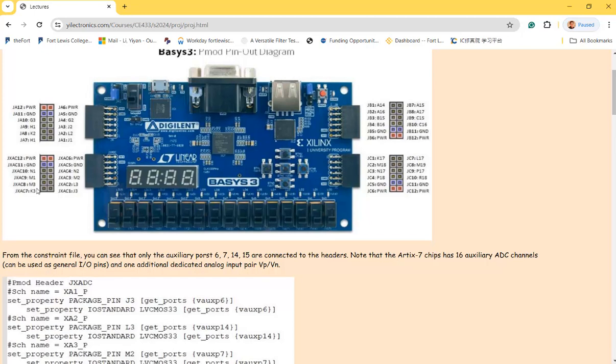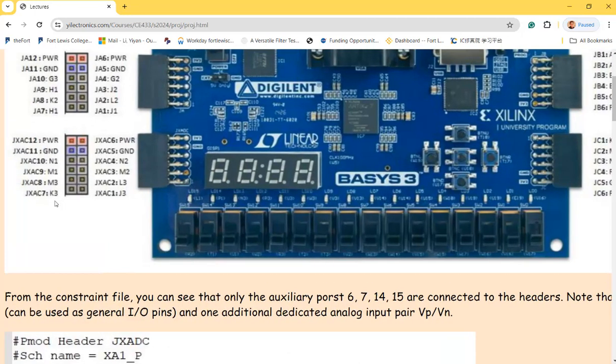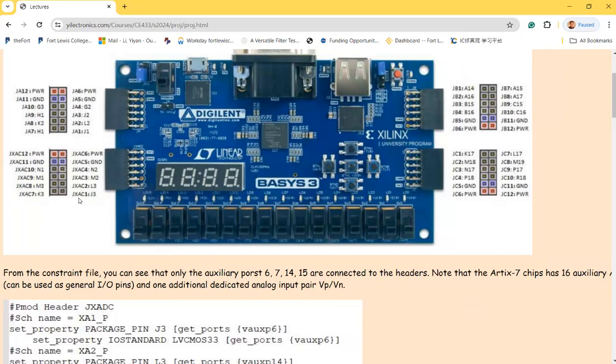So these are, I think, the pins available over here. And they labeled them with different names as well. But I believe these are 1, 2, 3, 4, I think. You can find out the map for these ones. But these are the analog pins, the ADC pins. Why is that? What do you think? The chip has 16 ADC channels, which means you can connect up to 16 analog inputs to the chip to do the ADC conversion. Right? It's pretty powerful actually.